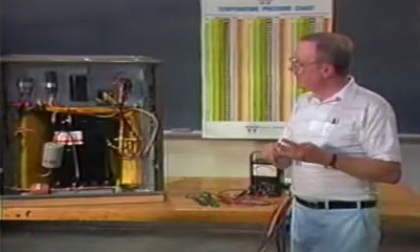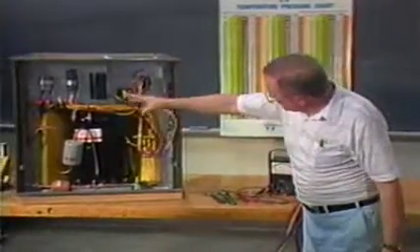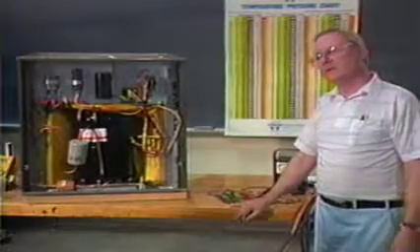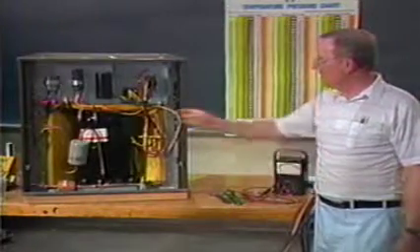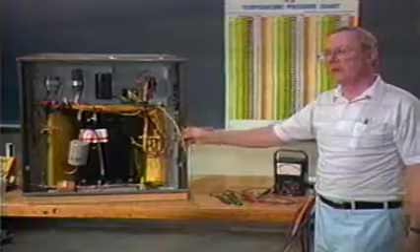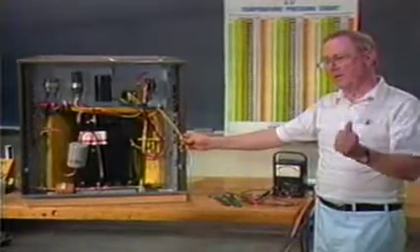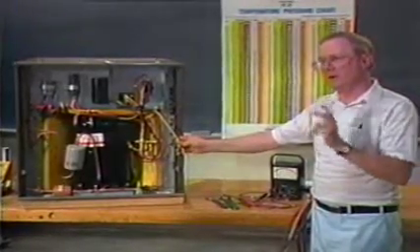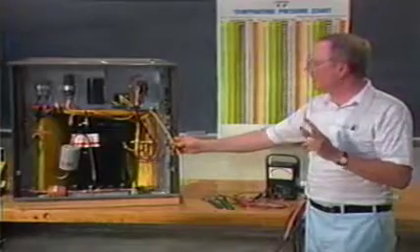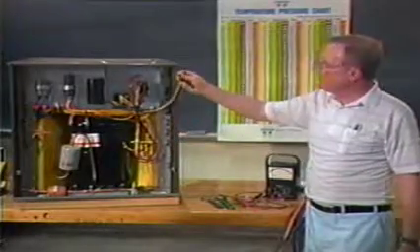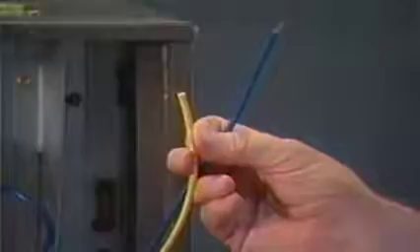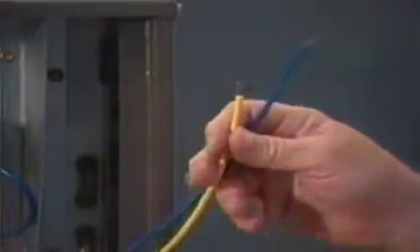Now when we get out into the field and we look at this mass of wire and so forth in this unit, we have a tendency to get confused. We need to be able to tie this theory of power supply, conductor, and load to practical use by realizing that the power enters this unit on these 2 wires right here. The power continues down the wire or conductor to the power-consuming devices, which would be called the load.